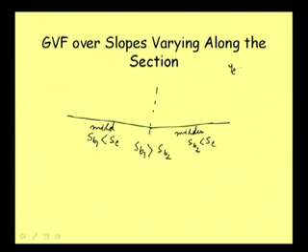Then critical depth, we know that this is equal to Q square by G whole to the power 1/3. So, for a given discharge Q, for a given bed width of the channel, if we consider this to be prismatic, for a given width of the channel, this Q is known or constant.